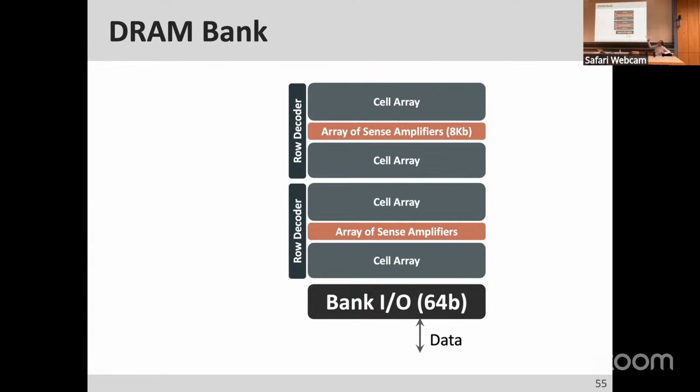You basically pick 64 bits of those 8 kilobits, and you have corresponding interconnects that route the data across the entire bank. Now, these interconnects need to be much bigger because they are covering a much larger distance. And those interconnects are also less efficient. Because they need to be much bigger, you cannot have 8 kilobits of them, because they're expensive.